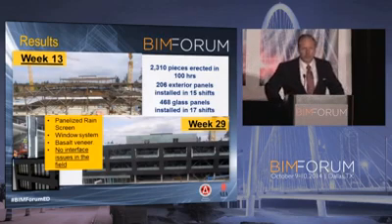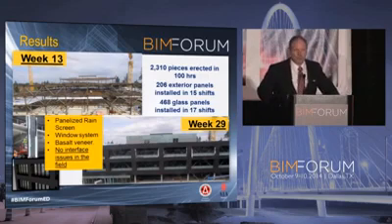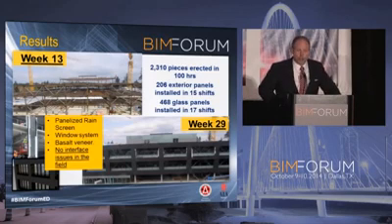The level of detail that we got to this was we set, again, the second most perfect thing on construction is glass. And we had the window openings set, the rough openings. And we told the drywaller we didn't even want the heads of the screws in that area. This is the level of detail you can start to get to. These are the things that you can start to think about when you're applying BIM.